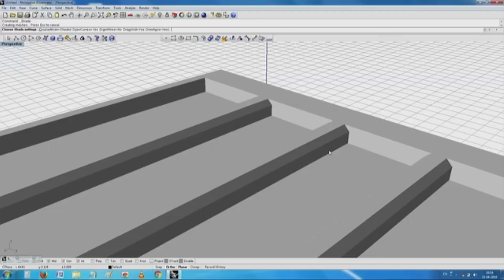This is very characteristic of any of these layup type of things, which has a distinct physical thickness, in that it cannot form a smooth plane as we think it is. So, you get something which is slightly jagged. Jagged means, depending on the thickness and the overlap and the rate of heating and rate of cooling and all that, this slowly starts building up like this.